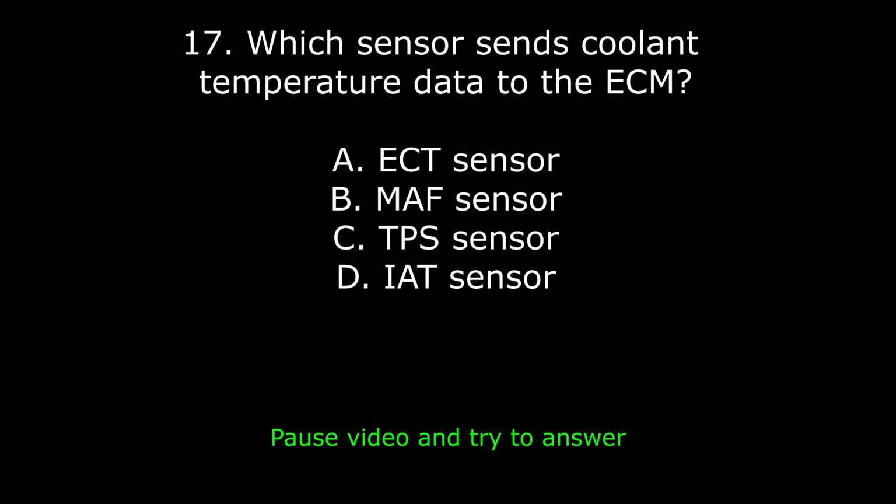21. Which component allows coolant circulation before the thermostat opens? A. Heater core bypass. B. Water pump. C. Pressure cap. D. Fan clutch. Answer: A. Heater core bypass. Explanation: the heater circuit provides a small flow path during engine warm-up.